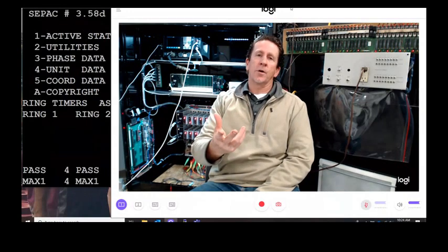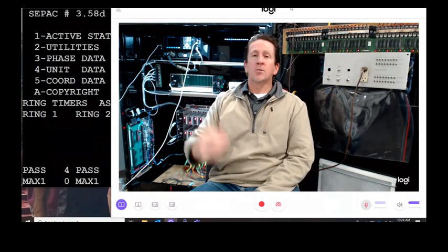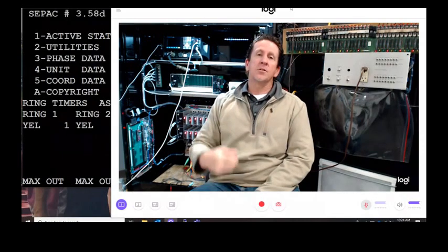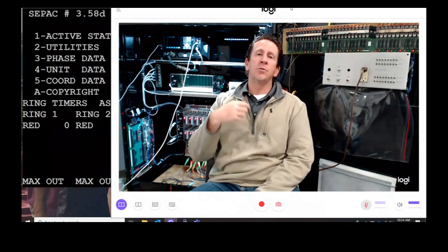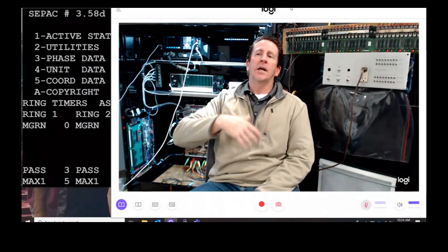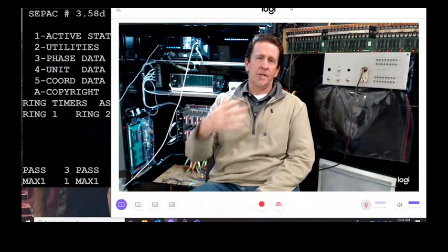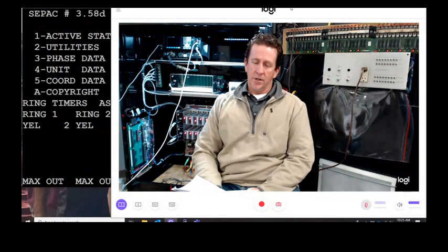When those burn out, that's when you get the intersection running and a phase 1 green or a phase 2 yellow seems like it stays on all the time. That means you blew the signal driver in the controller. It's a little IC chip in there. So it's still running, but it just stays on all the time, and that controller would have to go back for repair.